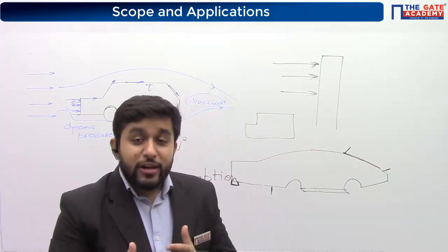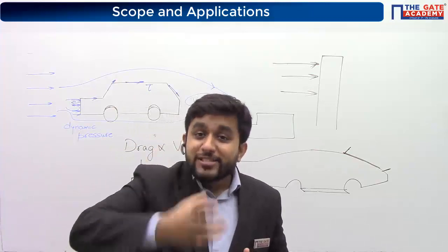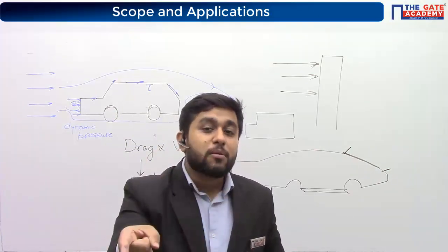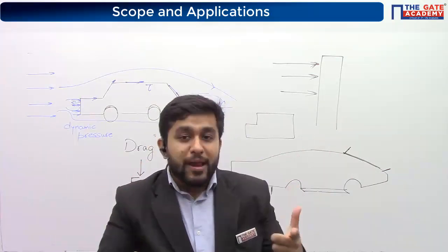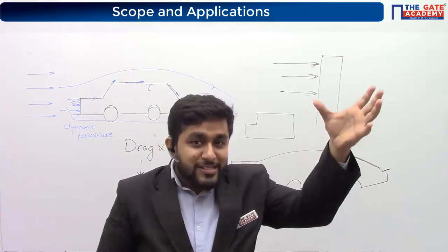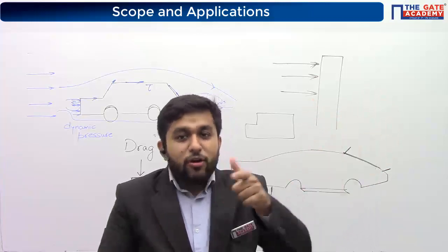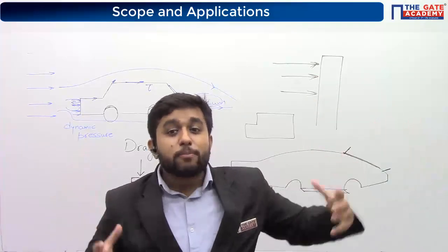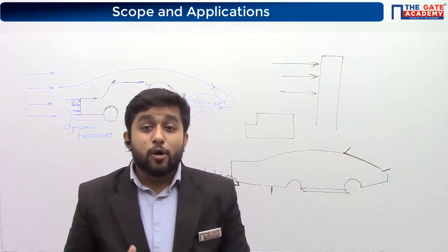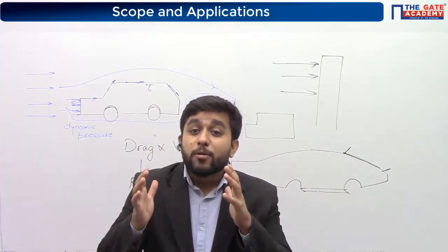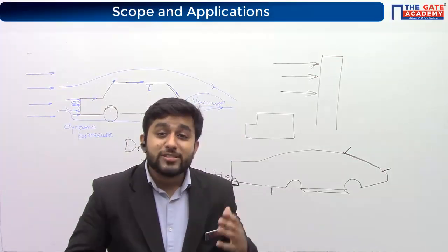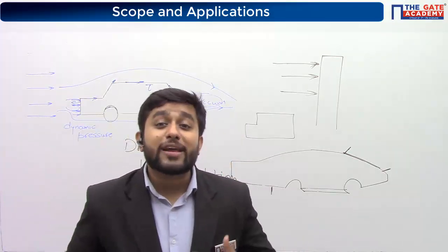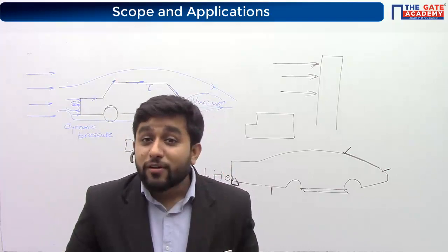Okay, basically what I am trying to say is that for every cycle there is a discharge to the combustion chamber, and if you do not design this air intake system in a proper manner, meaning the size of the components, the length of the components, the pressure drop in the components, you will not get a proper discharge and you will not get proper power production. So inside the automobile engine, whatever flow is there, whether it is air intake system or exhaust system, that is all based on fluid mechanics.